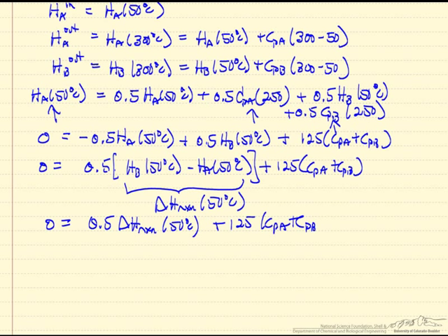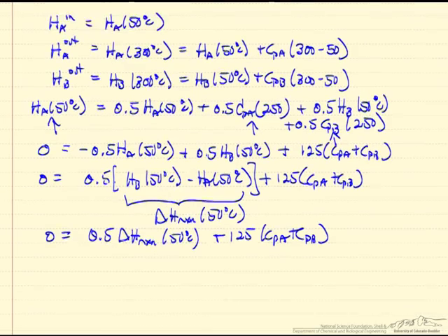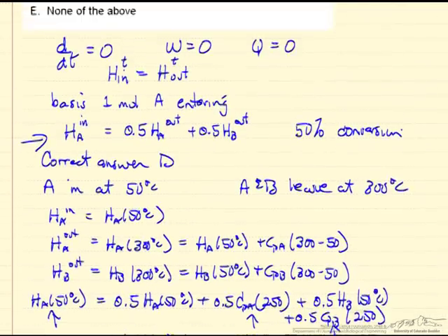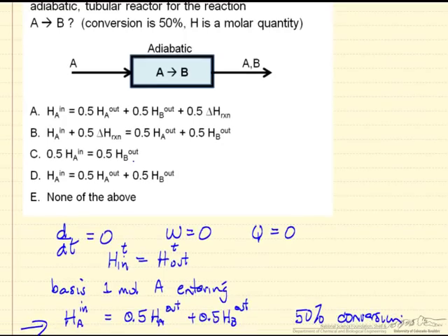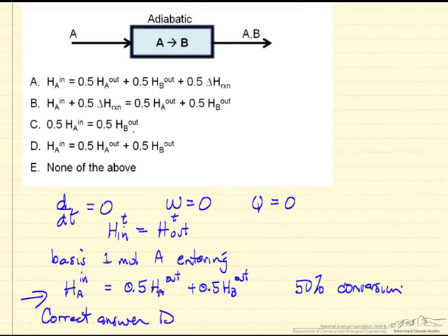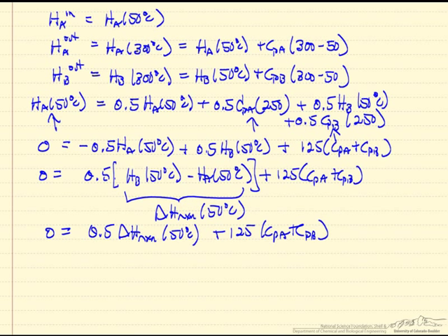But notice this follows directly when we start with the first law and just do an enthalpy balance. We don't have to introduce a separate term in this expression anywhere for heat of reaction for this reaction. Instead, heat of reaction drops out naturally. We do the enthalpy balance. Heat of reaction per mole, since only half a mole reacts, then the 0.5 term ends up here.